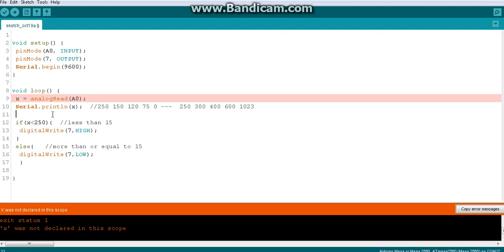Okay, that's fine. This was to control an LED. If the object is closer than the 15 centimeter range, the code will switch on a red LED to alert people. If the object moves away and is outside the 15 centimeter distance, then we switch off that LED. So that is monitoring, serial printing, and switching off.